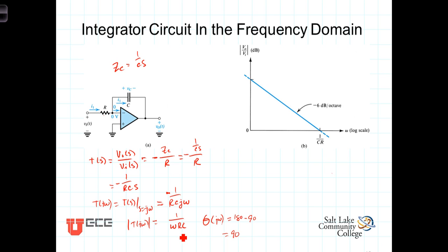Notice that the magnitude of the transfer function goes to infinity as omega goes to 0, or at DC. So the gain term at DC is effectively infinite. In practical terms, the op-amp is going to saturate if you've got any DC component to the input at all. The capacitor acts as an open circuit for DC, and there's effectively no feedback. With an open circuit here, there's nothing feeding the output back to the input to constrain the output, and the op-amp saturates. That's a problem.